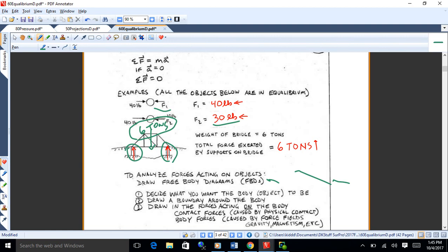Okay. Once we have the loads and the reactions, then we can find the total forces on the object, then we can figure out the stresses on the object, and then we can design it so it'll withstand the stresses. That's kind of the sequence here. So when you're taking a class in statics, they give you the applied loads, you find the reactions. Now that'll change when you start working. When you're taking the class, the challenge is finding the reactions.